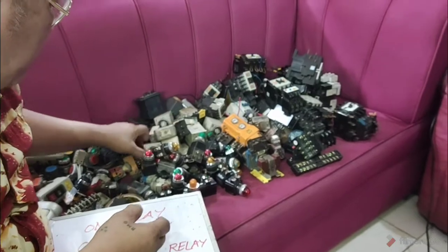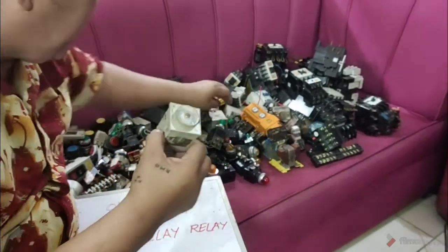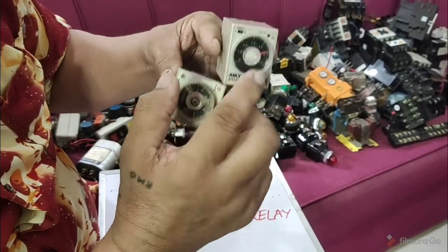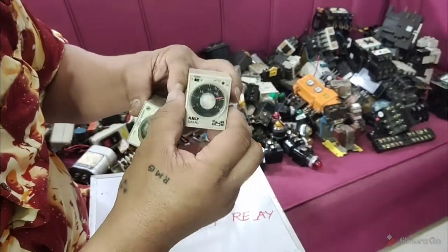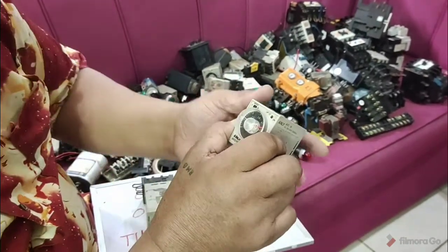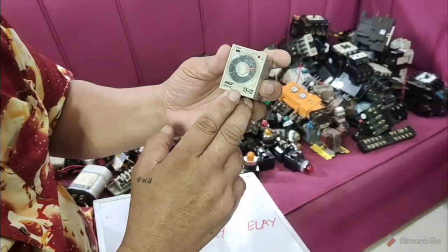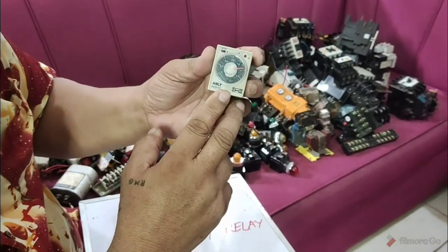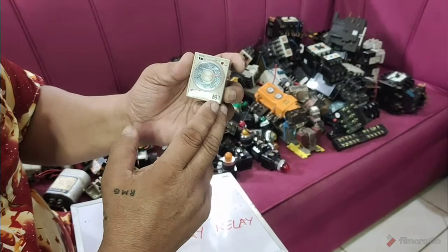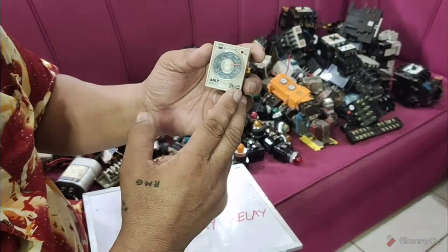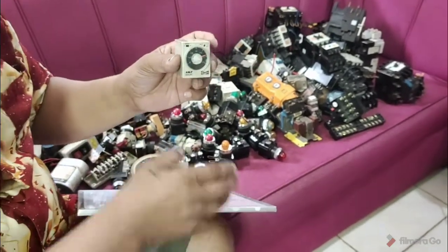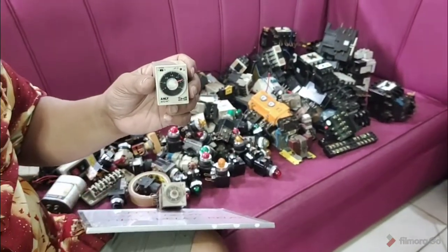And then we have also some other type here. It depends on the brand. We have the Anli brand. This is an on delay timer, and this is programmable. You can have this timer become a 60 minutes timer, a 6 minutes timer, a 60 seconds timer, and a 6 seconds timer. So this is programmable. It depends on your design of your circuit.